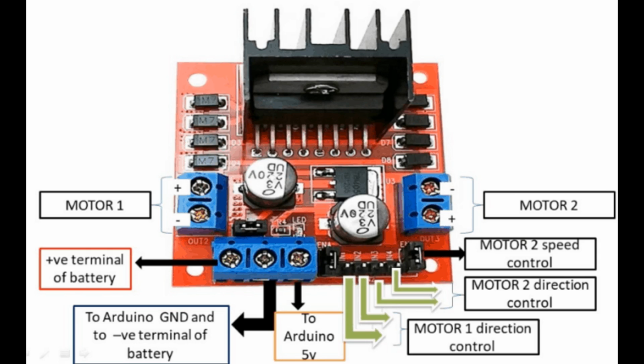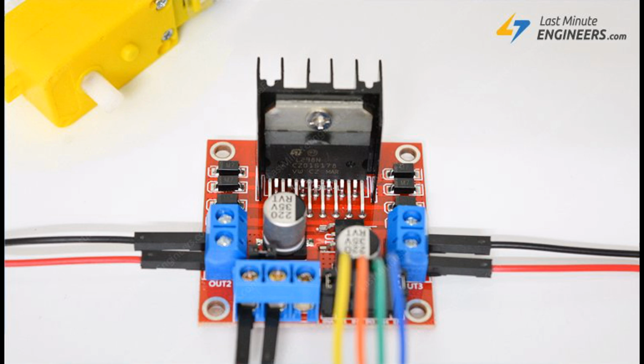Communication interfaces. Many modern VFDs support communication protocols such as Modbus, Profibus, Ethernet/IP, and CANopen, which enables remote monitoring, control, and integration into automation systems. 5. Applications of VFDs. Pumps. VFDs allow for variable control of pump speeds, which is useful in applications such as water treatment, oil and gas, and HVAC systems.